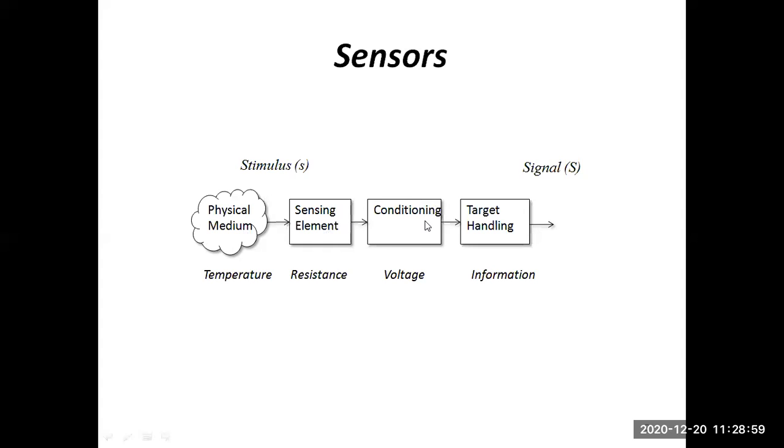And this voltage has to be adjusted in such a way that it can be fed to a device which understands a certain level of voltage. That is, let's say the device operates from 0 to 5 volts. So it has to be fed a voltage which varies only between 0 and 5 volts, not higher, and it cannot go below 0 volts, it cannot be negative, because that may damage the device. So in that case, we can be assured that this is safe for the device.